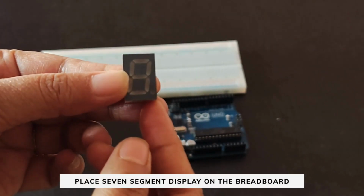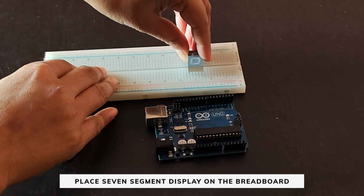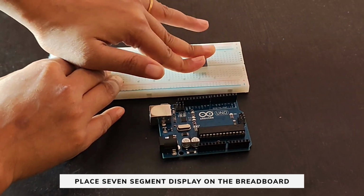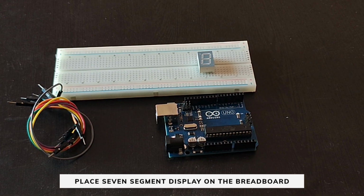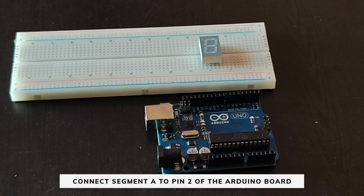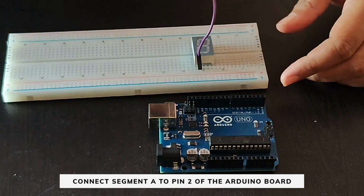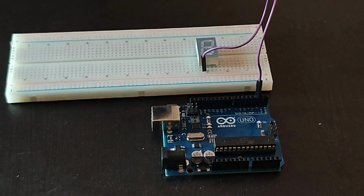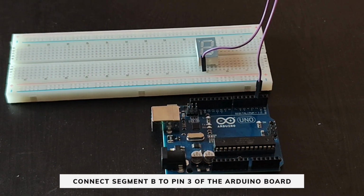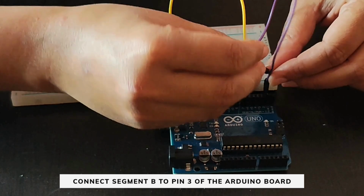Now let us place the 7-segment display on the breadboard. We will place the 7-segment display in the middle of the breadboard. And now we will do the connections with the Arduino board. So we will connect pin A to pin 2 of the Arduino, then pin B to pin 3 of the Arduino,